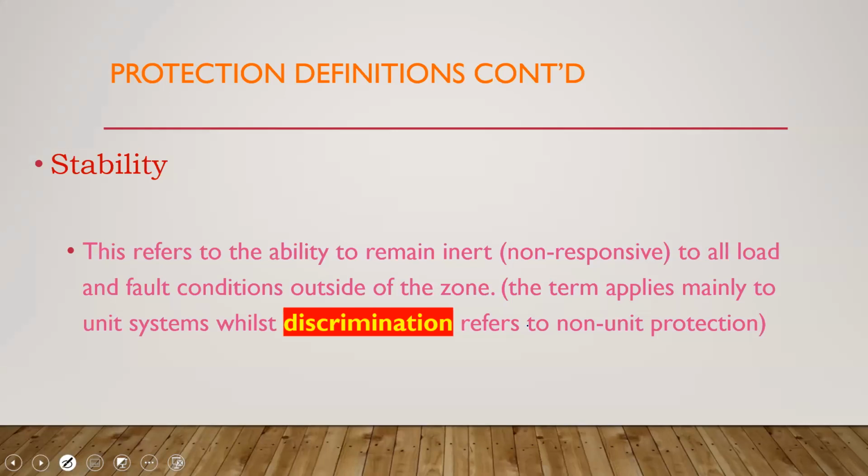Now we talk about stability. I mentioned unit systems earlier, but for stability, what we are talking about is the ability to remain non-responsive to all load and fault conditions outside of the zone. This really focuses on unit systems, because in time-dependent systems you would not have this in place. If it's time-dependent, it means that everybody would respond simultaneously, just that some respond slower than others. You with me? All right.